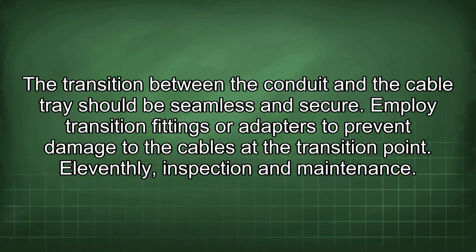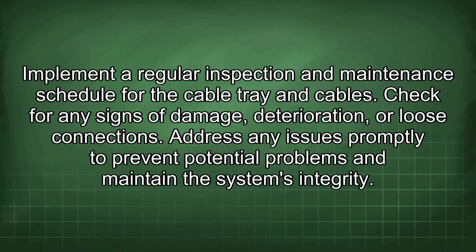Eleventhly, inspection and maintenance. Implement a regular inspection and maintenance schedule for the cable tray and cables. Check for any signs of damage, deterioration, or loose connections. Address any issues promptly to prevent potential problems and maintain the system's integrity.